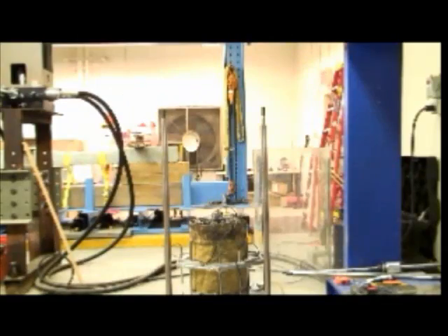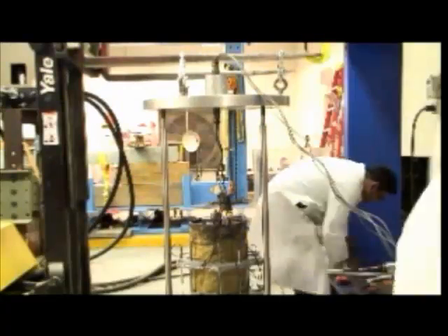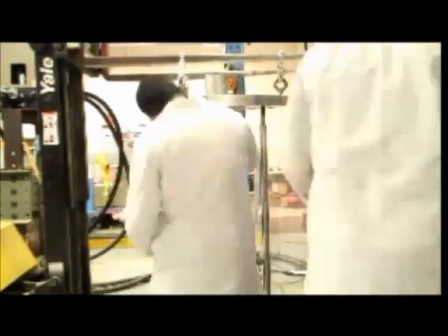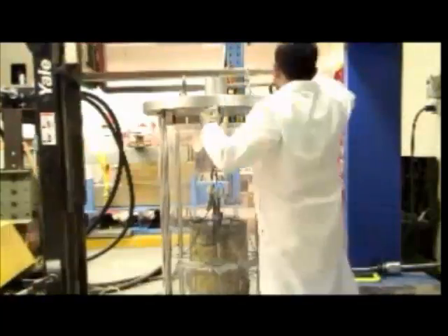Sure. The funny part about ballast construction is that there is no density check or anything in the field. They just lay the ballast and bring something called a drag stabilizer. They just vibrate it and whatever it is, it is. You can't use a nuclear gauge to test that, of course. It's a large topic, and people are working on how to study that. So that's the first point.